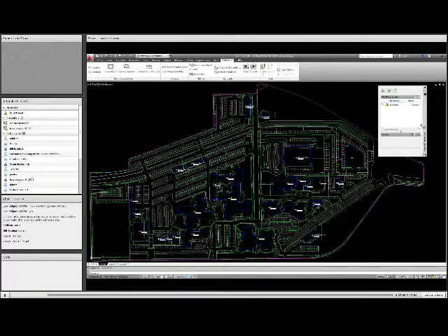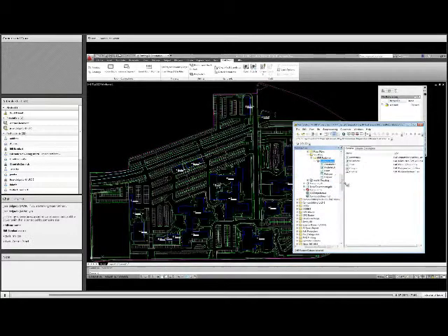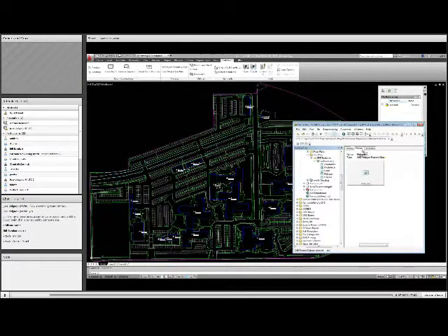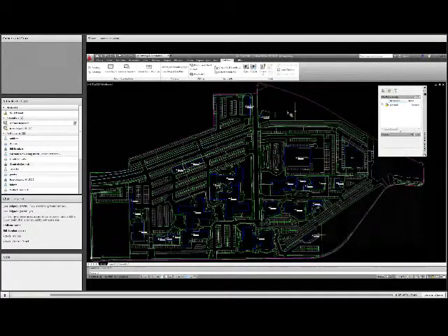So if I look at this site plan from an ArcCatalog perspective, I'm hoping everyone can see ArcCatalog. If not, let me know, please. Here is that same CAD drawing from a GIS perspective. You have your standard annotation, multipatch, point, polygon, polyline feature classes. Not particularly useful when trying to deal with real data. So what we do is convert these into our own feature classes that have data and really the way we wanted to work. So the first step in that is, let me bring it up real quick.